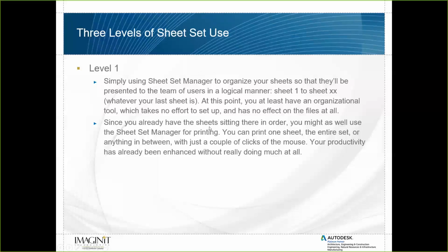Since you already have the sheets sitting there in order, you may as well use the Sheet Set Manager for printing. You can print one sheet, you can print the entire set, anything in between with just a couple of clicks of the mouse. And now your productivity has already been enhanced without really doing much at all. All we've done is add the sheets to the sheet set, and now you have the ability to print multiple drawings at one time with a couple of button clicks.